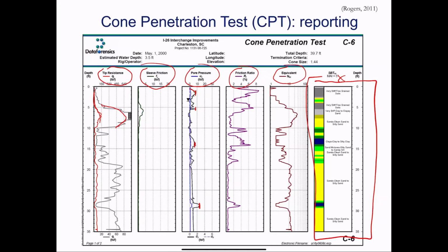As a good engineer, you should know what this N value means. Is it high, is it low, what type of soil? Is it CDG, what's the typical N value? CDT, colluvium, what's the typical N value? MD, what's the typical N value? So I hope this is useful.